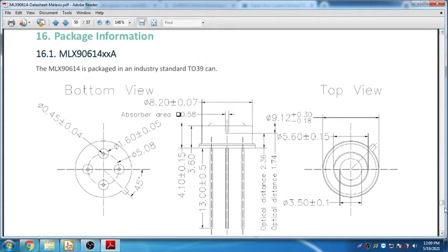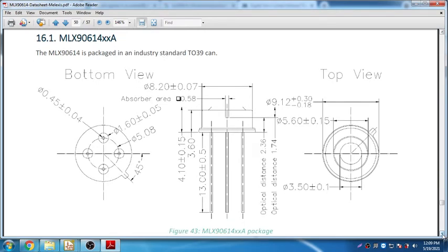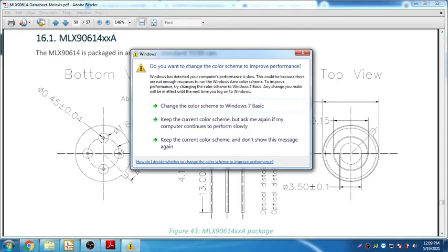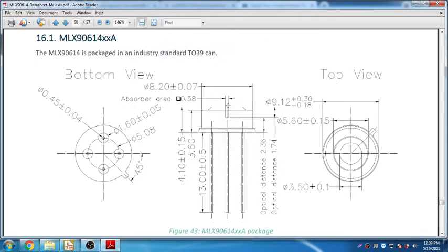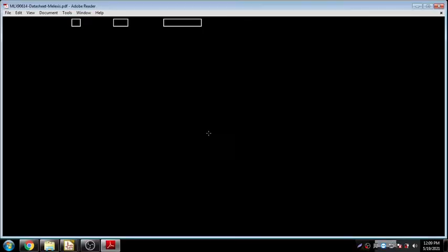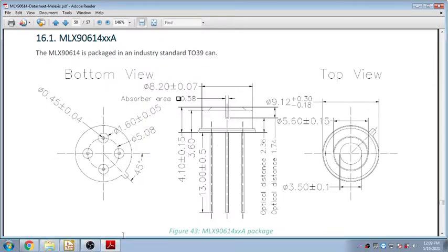So we need to design this. Let's look here. This particular hole is 0.45 and the pad is 1.60, and you see that arc, it is 5.08 mm, from this center to this center. So we need to define it in a similar way. Let's continue creating the component for this.